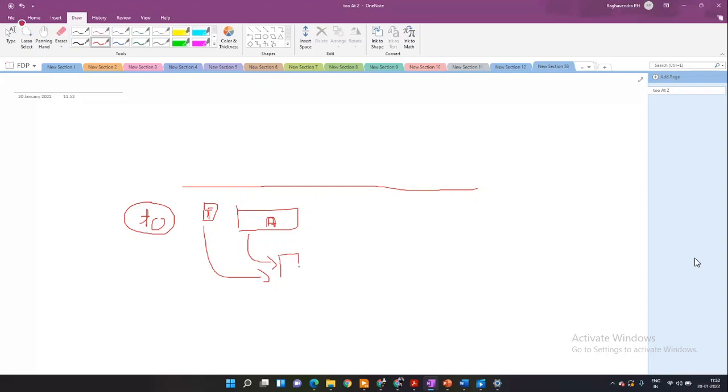If it is the same USB port, then you can be sure of this. If there are different USB ports, then there is a chance that this gets taken as T naught plus delta T. So your data is not perfectly synchronized, meaning the machine learning model that you build, I'm taking machine learning as an example, is not accurate. So you have all of these issues when you have a larger system of sensors or a larger number of data cards.